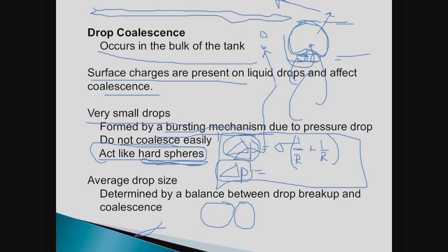If they're flat, if the hydrostatic pressure is very high, then these bubbles remain very much pancake shaped. And what then happens is, because they're pancake shaped like this, they all break. And so these large pancake shaped bubbles, you rarely ever see them. They may form initially, but they're gone quickly.